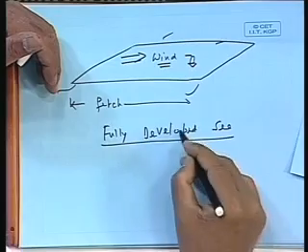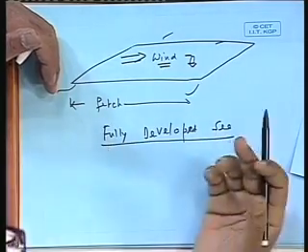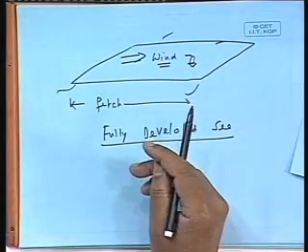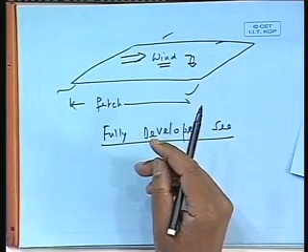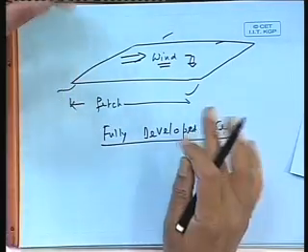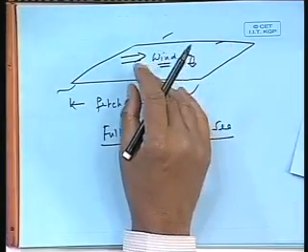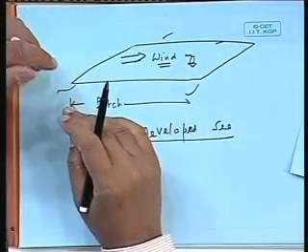Why do I say fully developed sea? It means that wind has been blowing for quite some time there. So, whatever energy from the wind the water could absorb, it has already absorbed. It's at a saturation level. So it has now created certain waves. So you can assume conversely that the energy of the waves remains constant for a given wind speed or a given wave state, because energy is a conservative principle. Initially, wind starts blowing and certain energy gets absorbed, forming certain waves. Sometime later more energy gets absorbed, but beyond a certain point of time energy cannot keep on getting absorbed, it has got saturated.